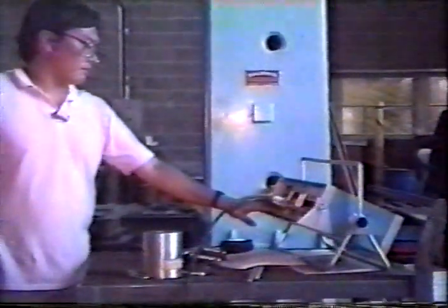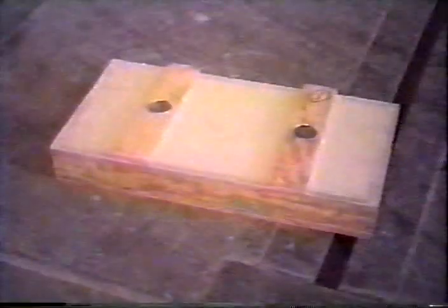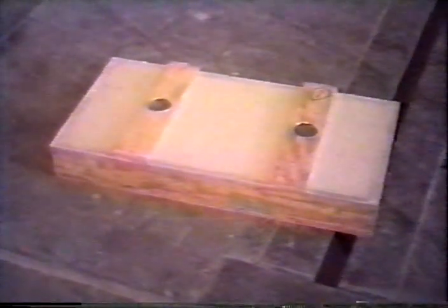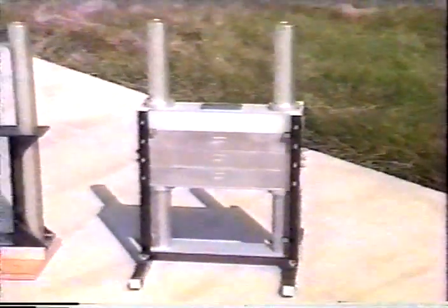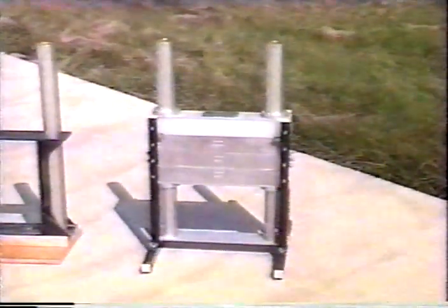Twin probe gauges must be calibrated prior to use in the field by determining the nuclear count rate of each of several materials at different and known densities. Calibration counts are determined on several hardened concrete blocks in addition to the polyethylene and 3-metal standard blocks supplied by the manufacturer. A steel calibration frame is used to hold the standard blocks and the two probes.